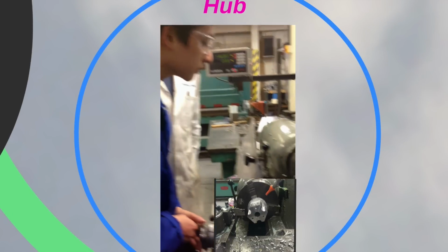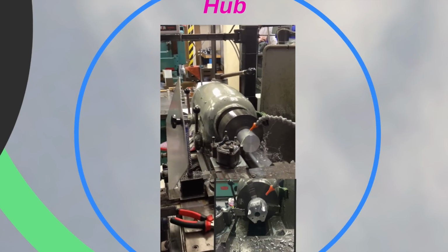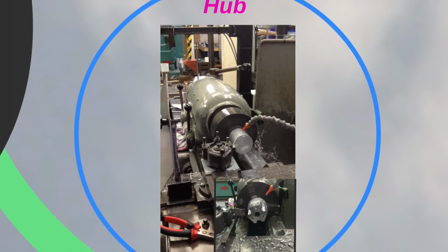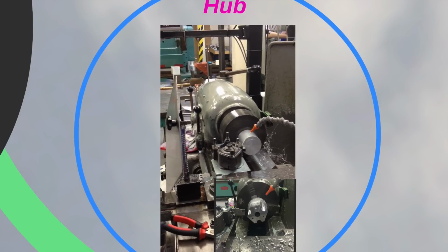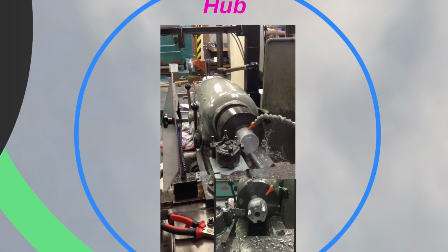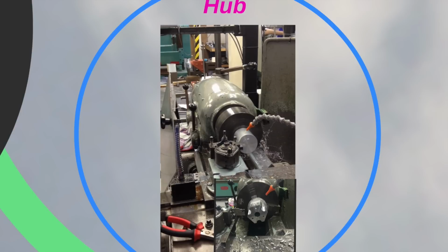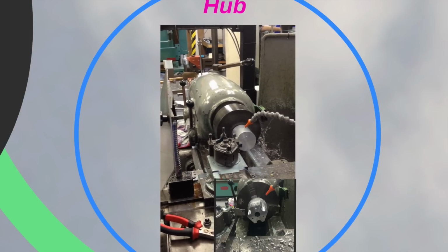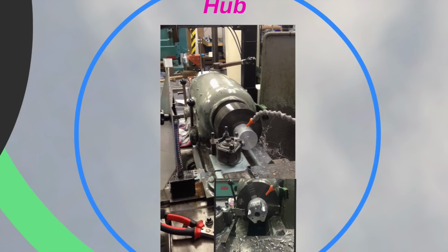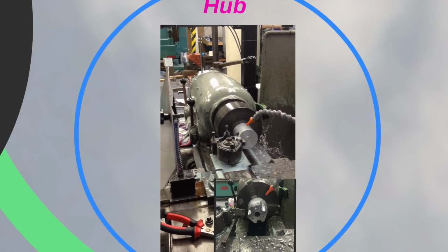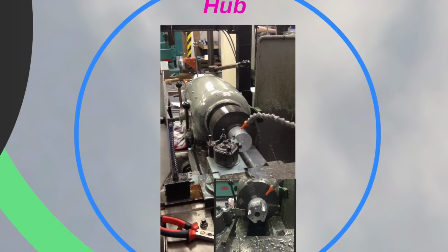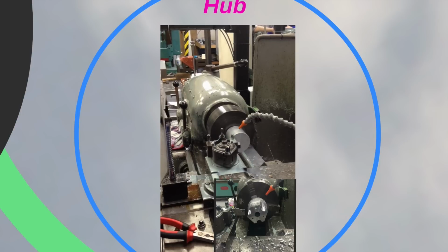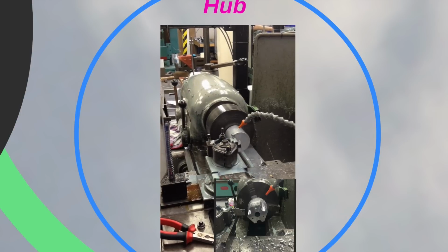The hub manufacture can be broadly categorized into 3 parts. The hub conceived initially was a cylindrical aluminum rod. The cylindrical hub was cut down to bring it to the size required. To prevent heating, a cooling agent was constantly sprayed while cutting was in progress. It was also ensured that the hub had a smooth surface. A CNC machine was used to cut the cylinder sides to make it into a symmetric hexagon, and drill holes so that the blades could be connected to the hub. Lastly, a keyhole was brushed so that the hub could be joined to the shaft during testing.